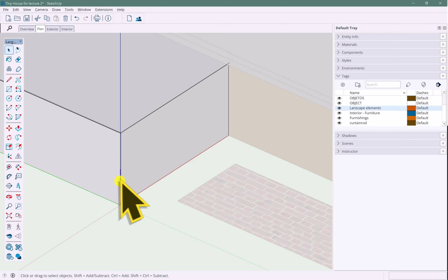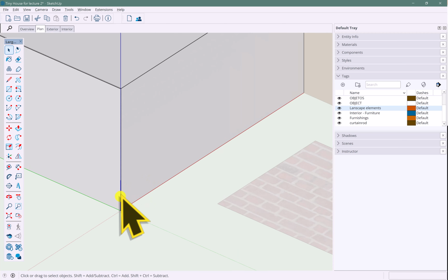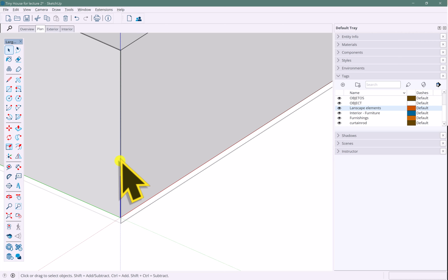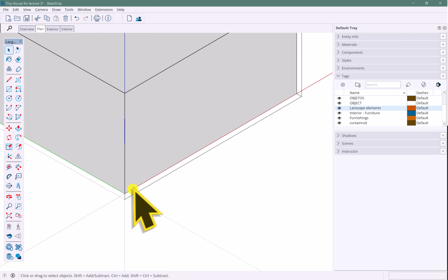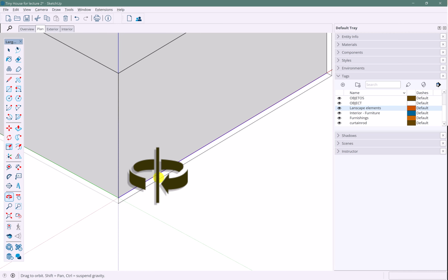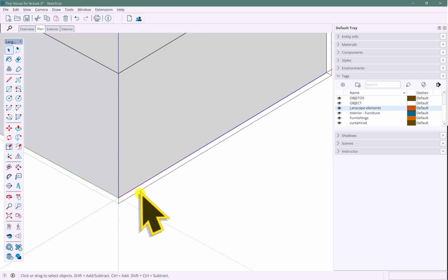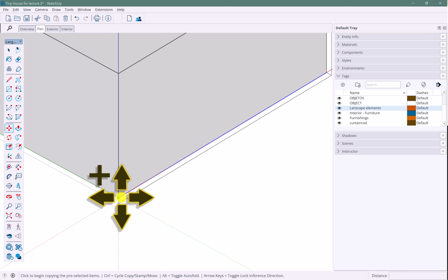And now you might say, well, hey, wait a second. I don't see anything different here. But what you'll find, just hide the rest of the model, is that there are 4 individual segments just on this one edge. Now I can take this bottom line and copy it. Again, we know how to copy, right? Use the move copy command, but then tap Control to make it copy.